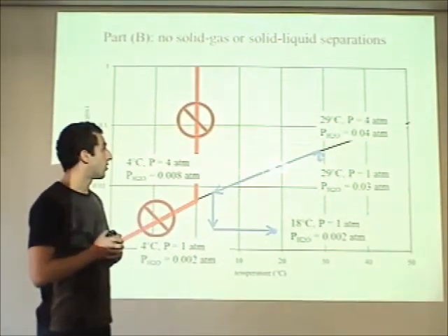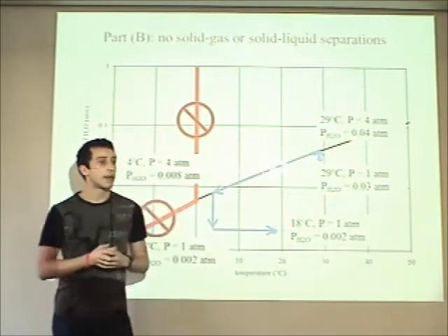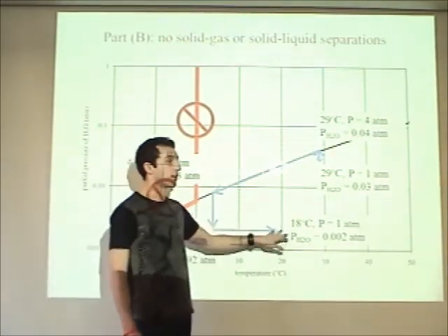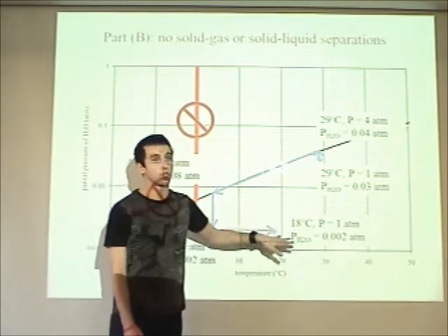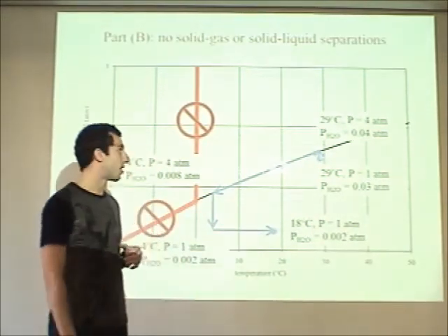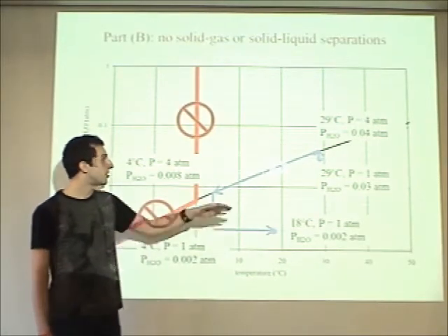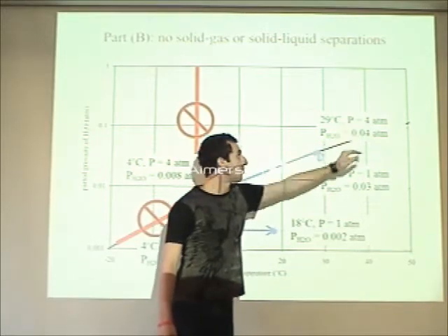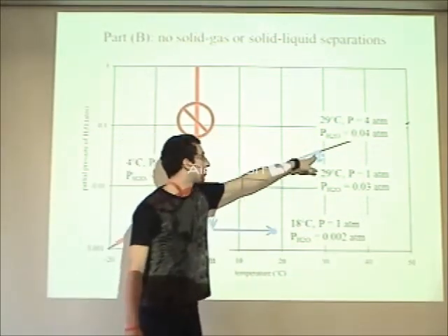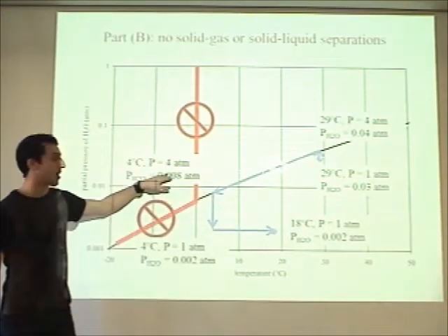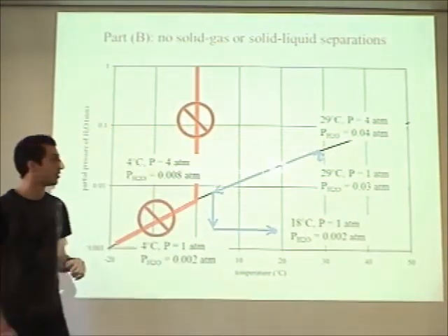All right. So the idea of all of that is we want to get the correct mole fraction of water in the final product. So this is drier air. There's an actual physically lower amount of water molecules in the vapor. And it's easier to do that if we first pressurize the total vapor mixture, because then we have to cool it down less to reach the same mole fraction that we want.